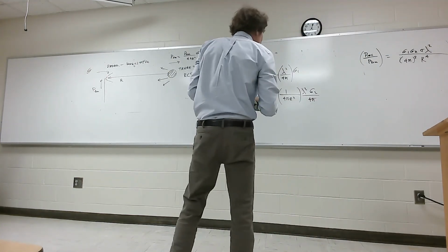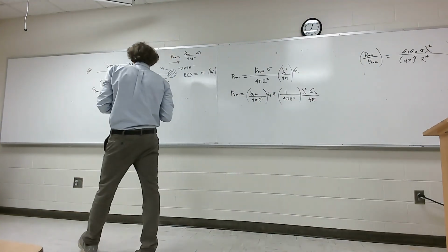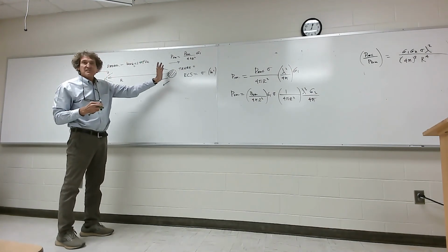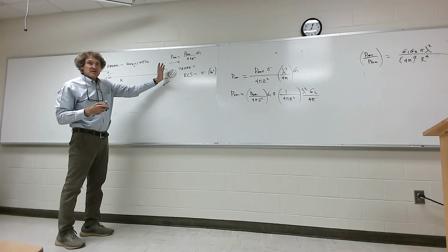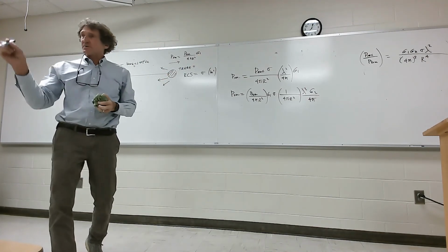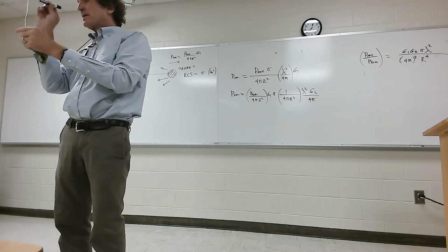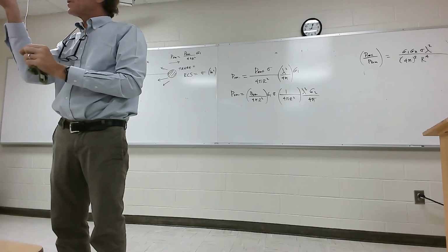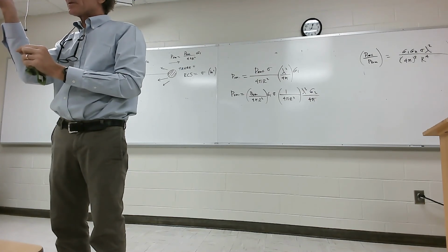Obviously, you can get things where, and I'm not going to spend too much time on this, the RCS of the object is a function of the angle of incidence. For instance, if you have an aircraft or just a long missile, and you look at it head-on, physically it's small, looks like a dot coming at you. If you look at it from the side, it's much larger in terms of its cross-sectional area.